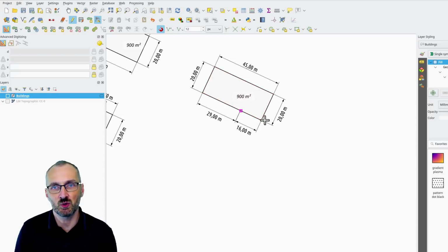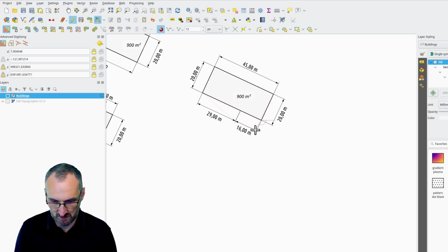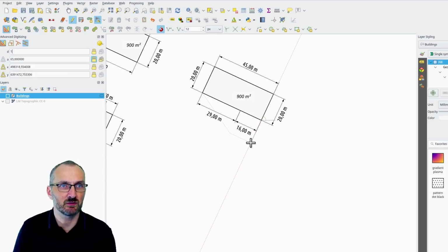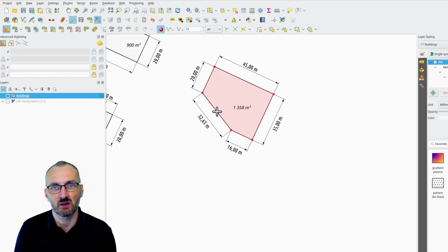And then I want to move it out in this direction. So select those 2 points and move them in parallel to that line. And let's say 15 meters. Distance 15. Confirm. Need to add a point right here.